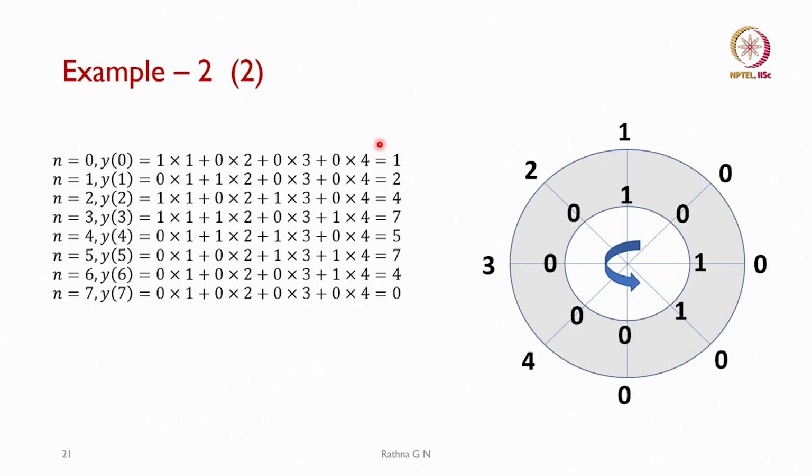So, I showed you how it has been done in the previous example. Same way, if you do it, you will get this value. The last one will be 0, which you can discard and then keep these L plus M minus 1 values for your result. So, you can see that we have taken a little bit of DFT to show the circular convolution property. Other properties you can look into the book and then come out with it.